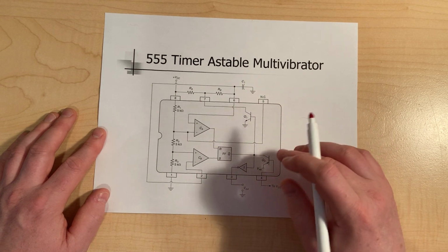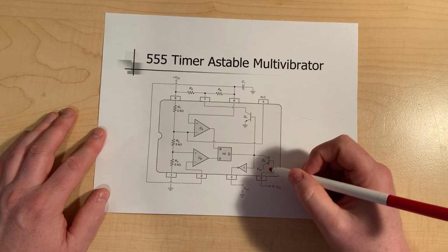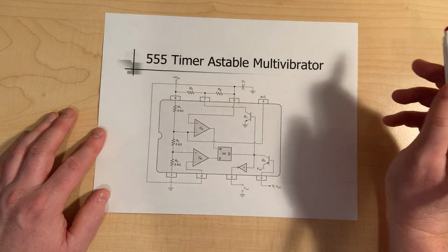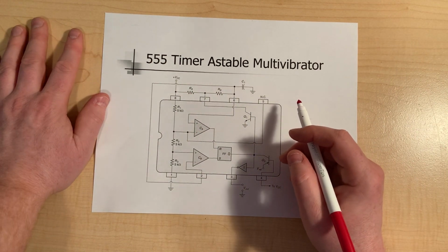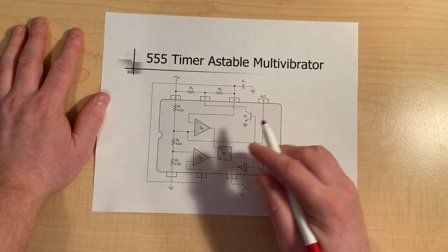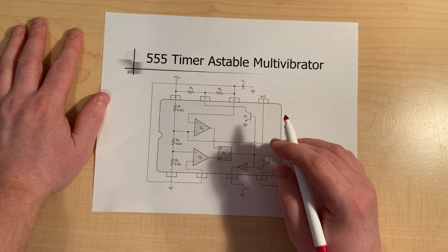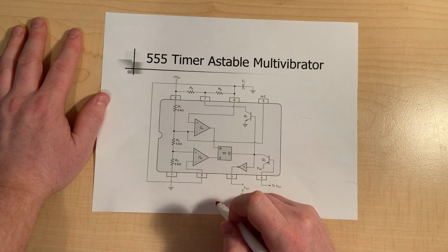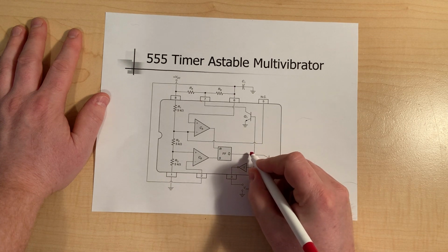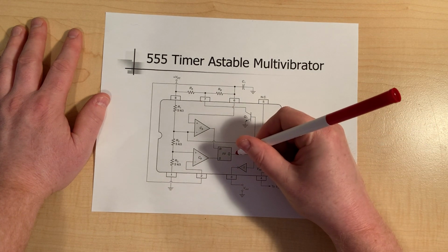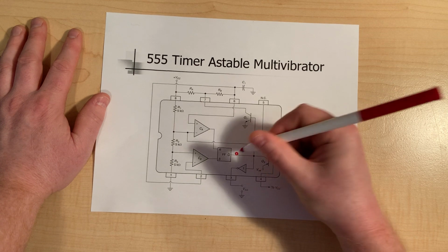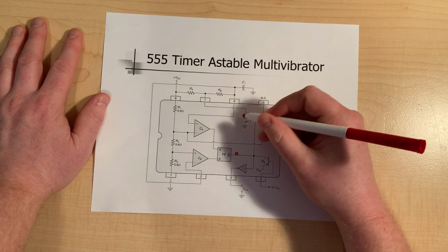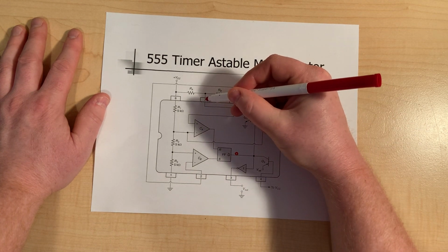Let's just imagine this for a second and go through the cycle here. Notice that we have resistors here and here. I'm going to just pick a state. The first state I'm going to pick is that Q0 is low. I'm just going to say that this point is low. So let's start with this point. We'll say this point is low, just put a 0 there. The low doesn't turn him on, so we have no ground at pin 7.